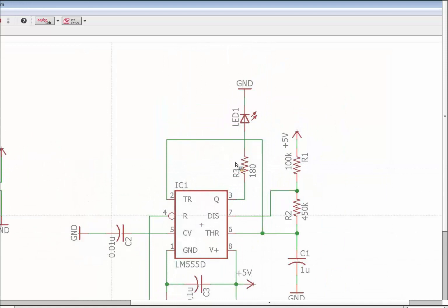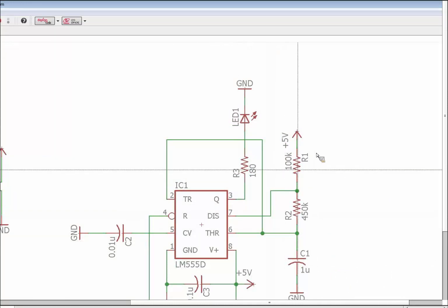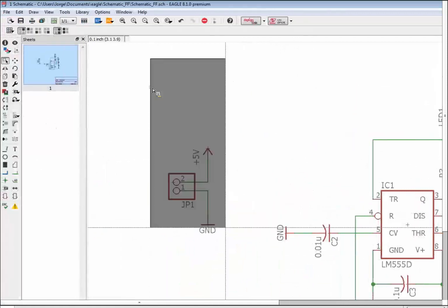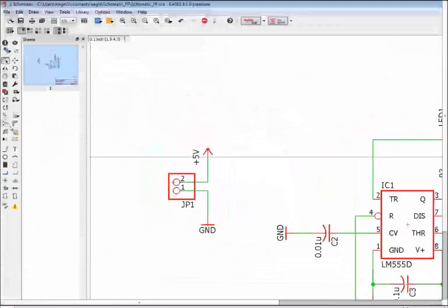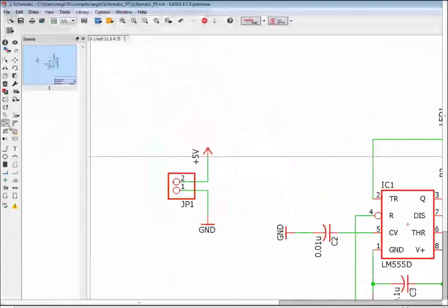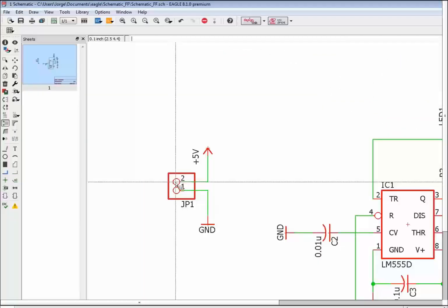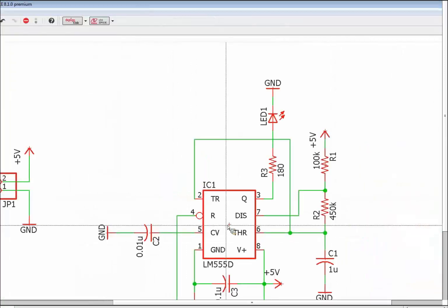If you need to rearrange the text because of space constraints or just to make things look nice, then the best thing to do is just do group on everything. Select the smash command, which is this one over here. And then if you just left click, it's going to apply it to whatever item you left clicked. If you want to apply it to the whole group, you're going to hold Control. If you're on a Mac, it's the Command key, and right click.